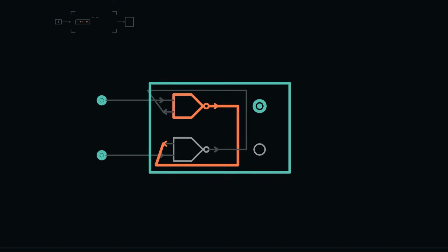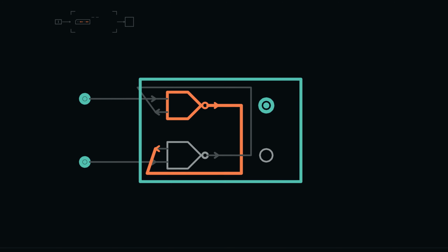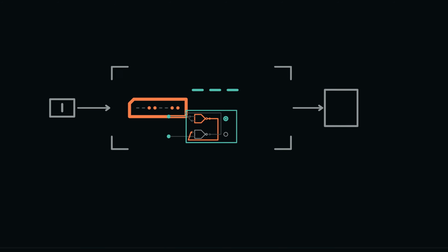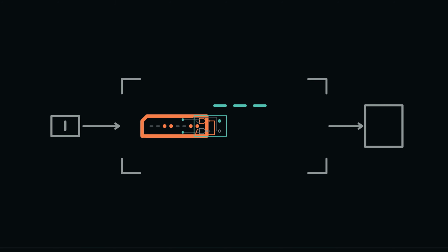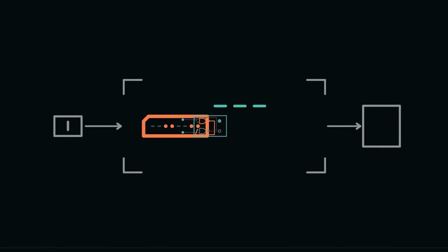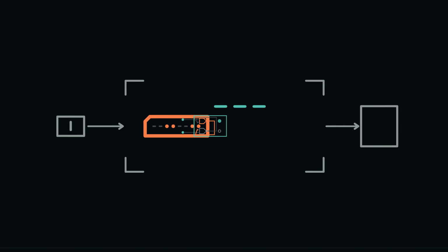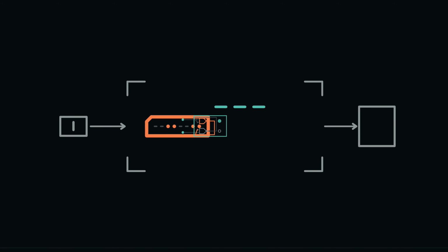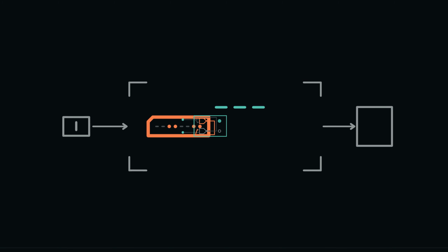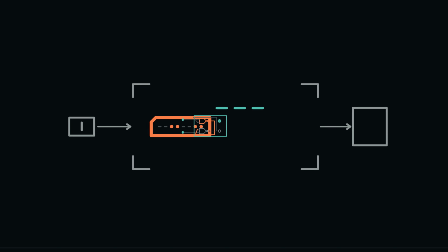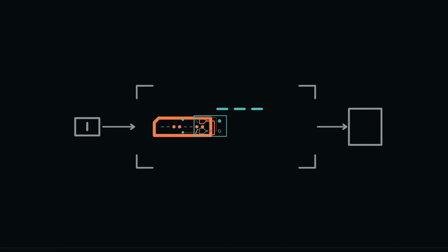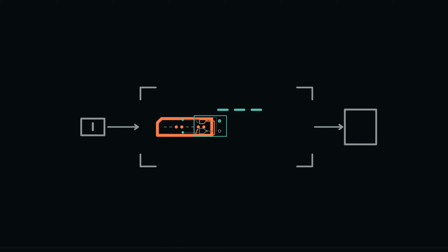The cross-coupled gates close into a 1-bit storage outline, but the before and after ledger remains beside it as proof of history. We can set, reset, and hold a state. What we do not yet have is an orderly moment when many storage cells agree to accept new values together. If control changes arrive at arbitrary times, a larger machine becomes difficult to reason about. The next chapter introduces a shared event that separates old state from new state without pretending that physical change is instantaneous.